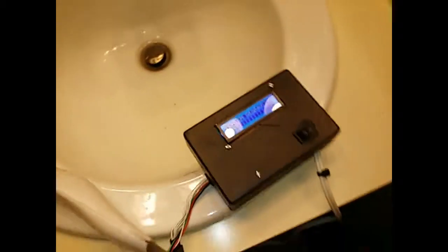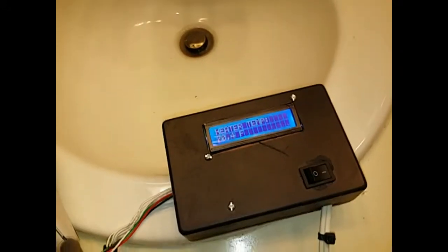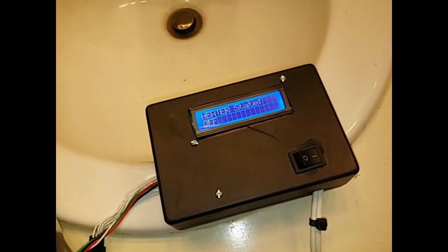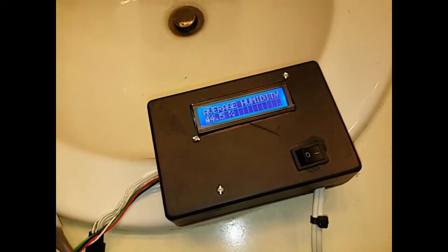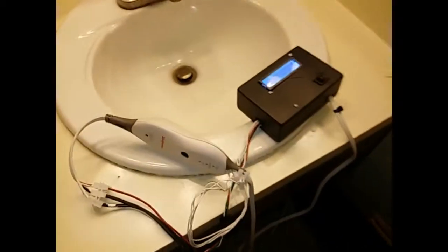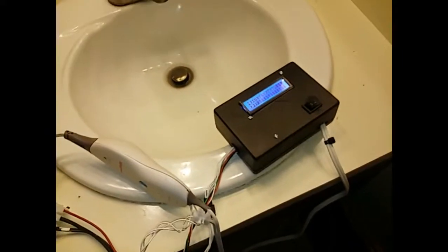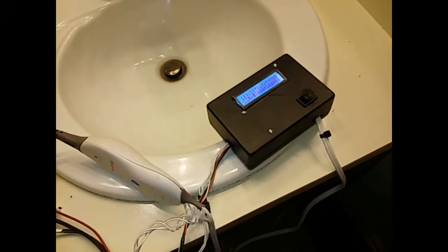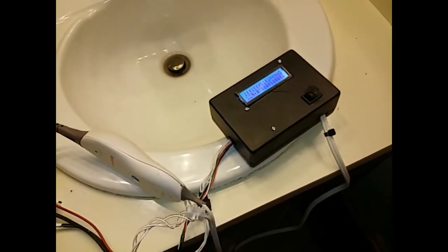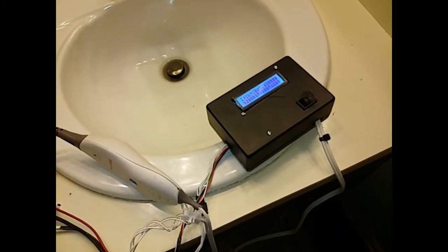So what I do is I have it set so that when the current humidity reaches an elevated state of 1.1 times the average humidity of the last 10 minutes, it will switch the heater on. What I'm going to do is run the shower, and I'm going to pause the video while I do it for time's sake, and then I'll show you what happens as the humidity rises.